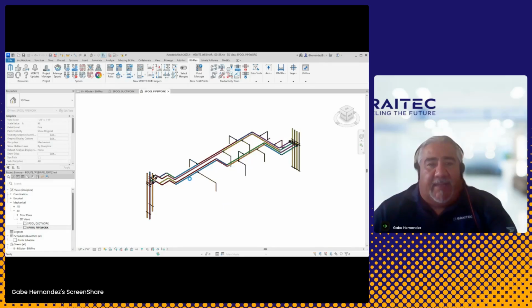But once these are created, I forgot to go over the actual settings for naming conventions, so you can kind of see this here too. But I did the numbering after the fact, right? Fix the numbers in the spool manager, which is okay because there's tools for that. But you could also set this up ahead of time to meet your company standards as well.